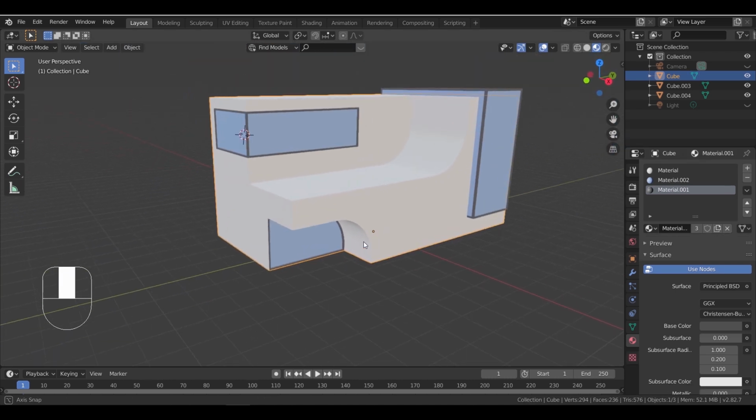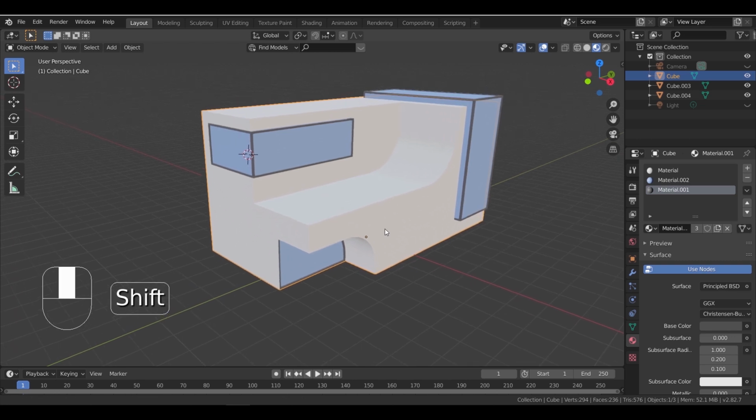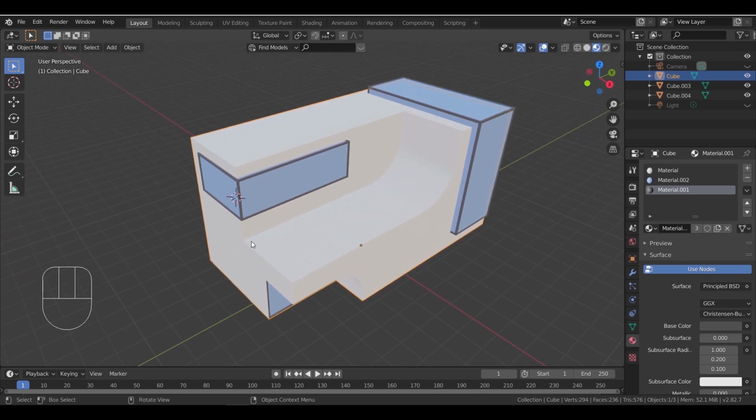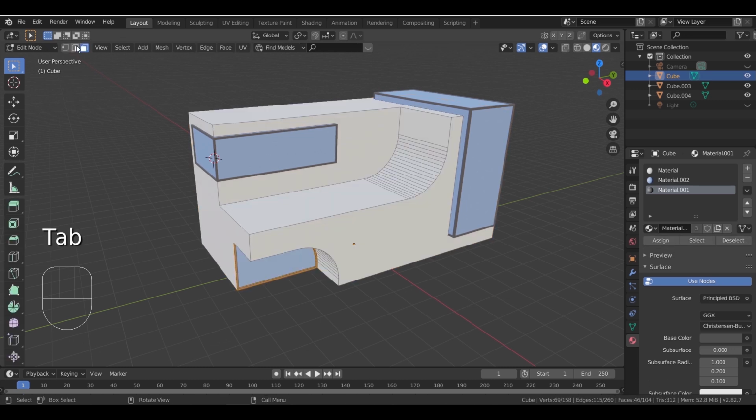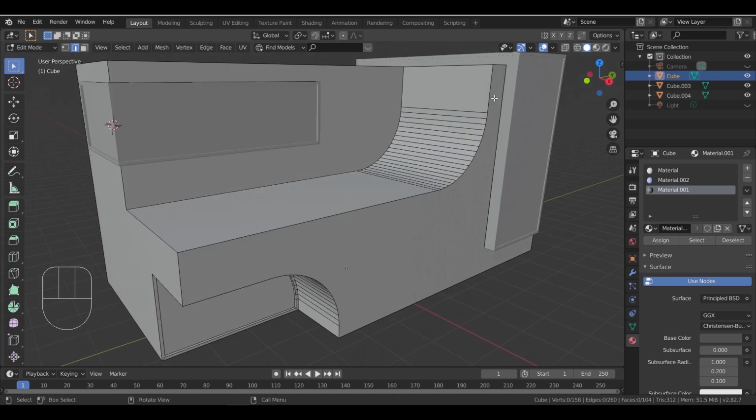So, if we consider this area to be a balcony, we sure need a railing here, and there are multiple ways to do it. The one we will follow is like this. In edit mode, make sure you are on edge selection, then you select one edge of the balcony and hold Ctrl before selecting the one near it. This way we highlight all the curve to the corner. The other part of the corner you select by holding Shift.